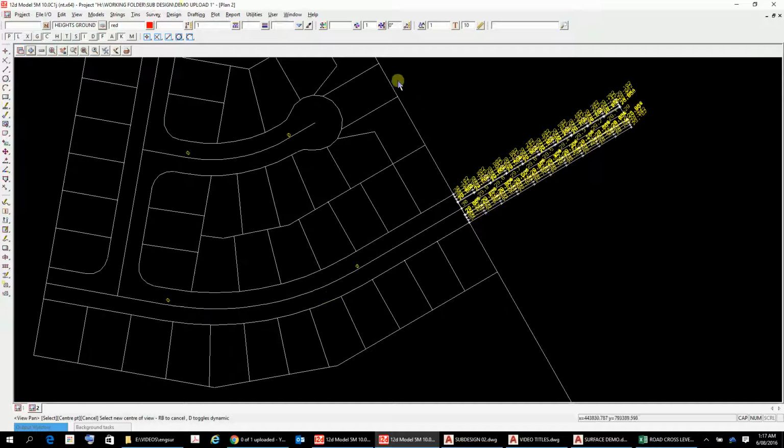I also want this point here to be higher than this road and higher than that road. So if that's 30 there, I might say, for instance, let's just say 33 there, and we'll put that in there. So to put a point in there, I can just click on the point value here. Oh, I've got to put in the height here, so just type in 33 like so, and then click on the point here, and that will put a point that's a cursor snap. So click and accept, and there's a point 33 in there. So 30, 33 up in here.